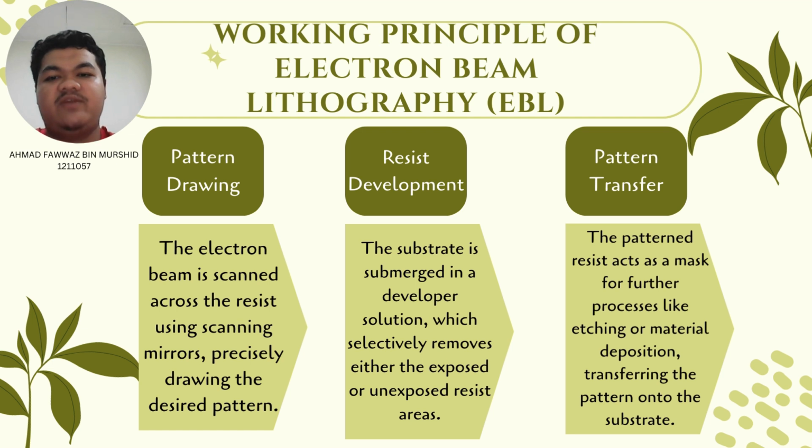Next, for negative beam resist, the exposed area becomes less soluble and the unexposed area is dissolved by the developer. Common developers used for negative resist are a methyl ethyl ketone and ethanol mixture, and also xylene, which is sometimes used as a developer for negative resist, especially if it has thicker layers.